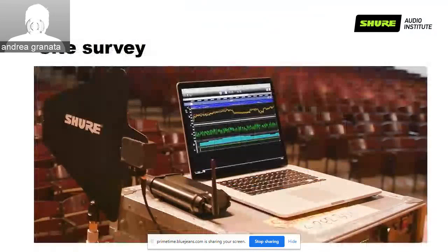As we said, RF noise floor is a very big part of our equation when we do coordination, and it's usually the starting point. How do we come to know what is the noise floor of different frequencies? With a site survey and with an analysis of the spectrum. So to analyze the spectrum, we may have different devices that operate in different ways, but ultimately we need to know what's going on in the spectrum.